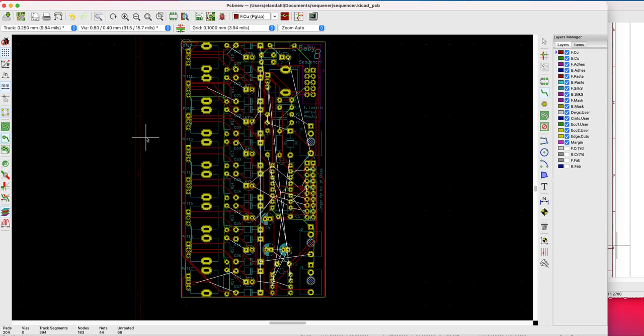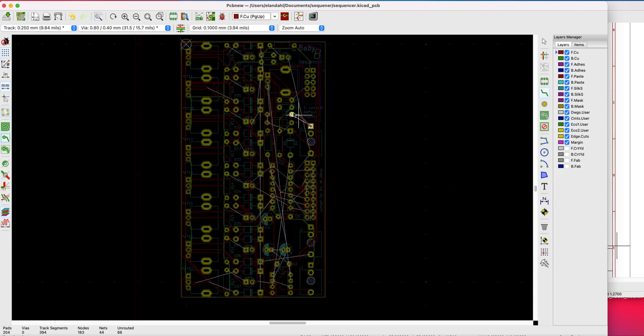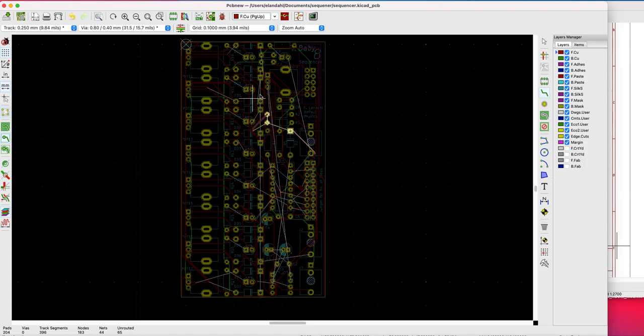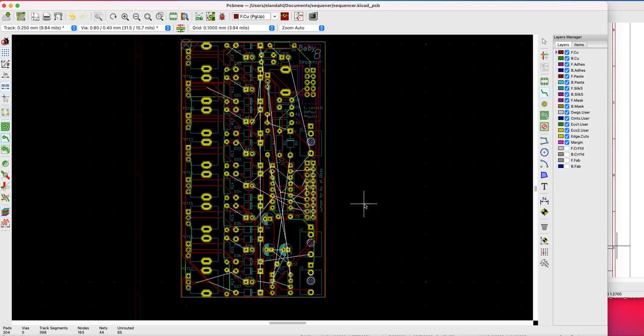So after some clicking, you'll find you have significantly reduced the amount of rat's nest and significantly increased the number of green and especially red traces. But you're not done yet. There's still lots of white traces indicating rat's nests that can't be completed, and even your best attempts to do so will often be met with failure, because there simply is no route that the software can find to get where you want to go that doesn't cross other wires. So, since you can't cross wires, you have to go back to the other side.